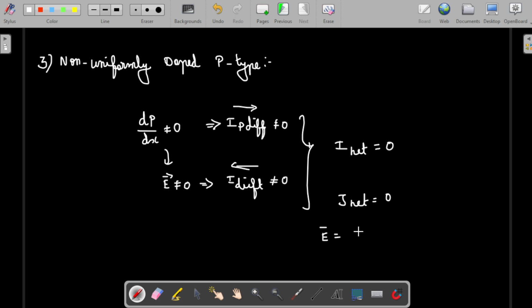Extending from n-type to p-type, we get the same formula with Vt as the reference. There was a negative there, but here no negative, because the J diffusion is taken as negative, so that value will not be repeated. Then ln of p of x. This is the equation that we finally get. I think you are familiar with this because we already derived it for the n-type.